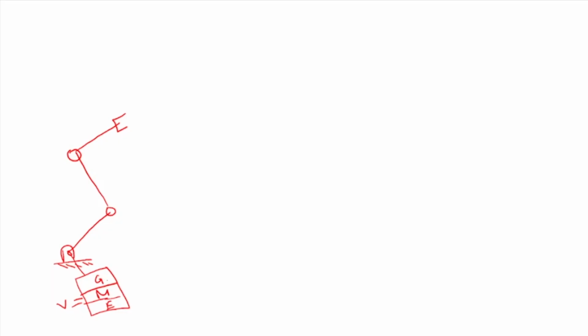So if you want to go from some point to some point, let me say the manipulator is here, and I want the links to go there. Just for example, I want the manipulator to do like this. It essentially means that this link has to move by this much angle. The second link also will have to move, and the third link will move by some angle. So theta 1, theta 2, theta 3 will all move by some angles. The controller has to move the links by the corresponding angles so that the end effector comes from this point and reaches that point in some time, let's say time t. So the controller needs to know by how much angle each joint has to move, and that we can get from the inverse kinematics.